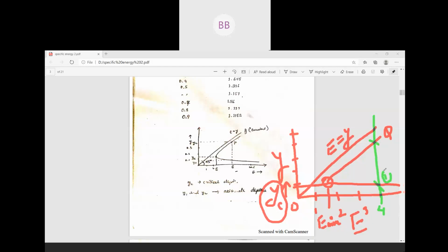That is one point and it is another point. If you consider 4 meters of specific energy and draw a straight line, along that line your specific energy is 4 meters. That is your x coordinate, and this line intersects the graph at two sections, one and two. For section 1 we have one depth of flow, and for section 2 we have another depth of flow.